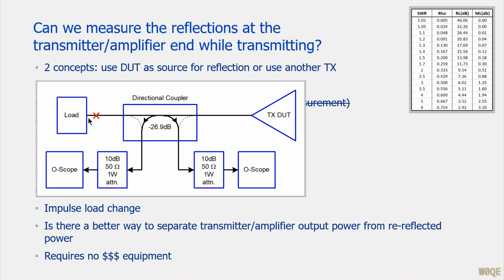And then I very quickly do something out here. This would be tantamount to your antenna breaking a loose connection or something like that. And the transmitter may do something, but it's going to take it a millisecond or so to do it. In the meantime, I've had plenty of time to look at the signal here with the scope, and I can capture it. So try to follow this logic.